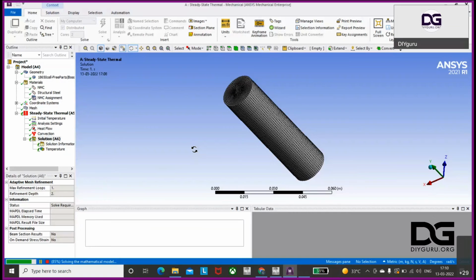Sir, did you slice this geometry from between? No. What happens is the one I've shaded in my SolidWorks gets sliced over there. But if you want to slice it into 4 parts as well, you can go to the geometry part and click on edit. In SpaceClaim, you can use Design Explore. You can slice your geometry by using the plane. Okay, sir.